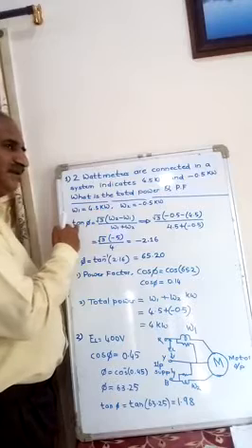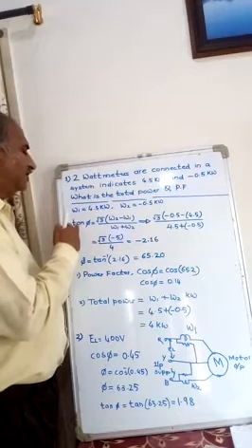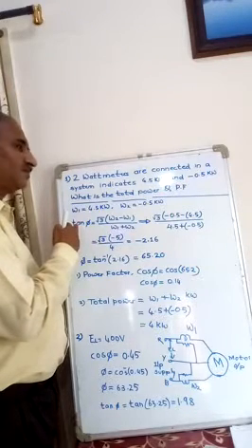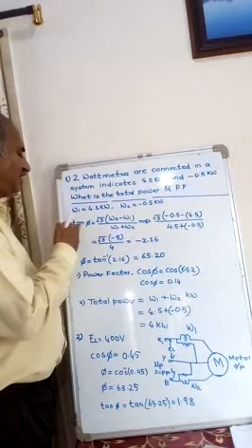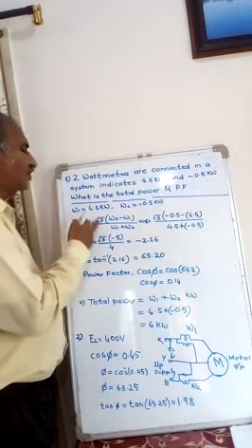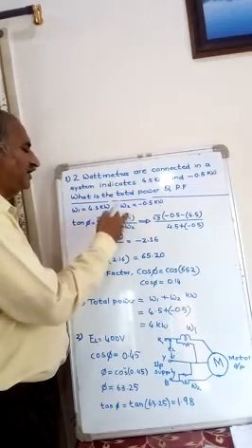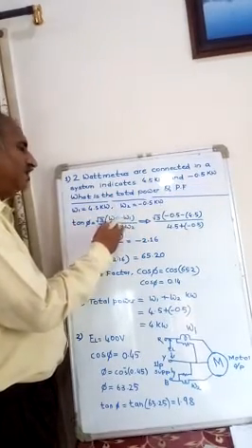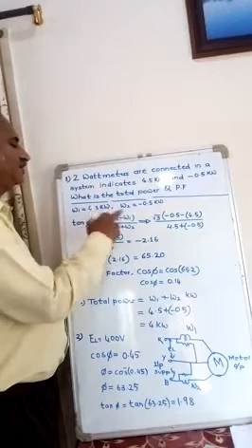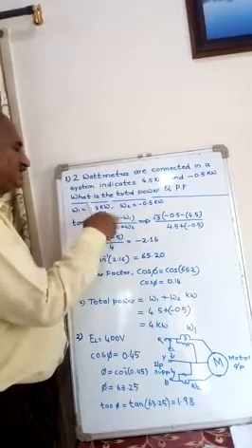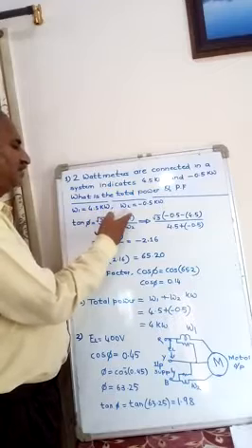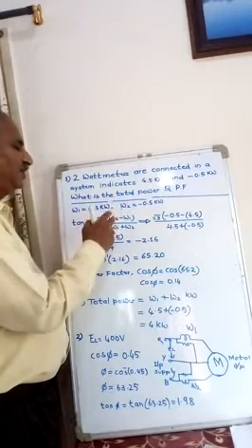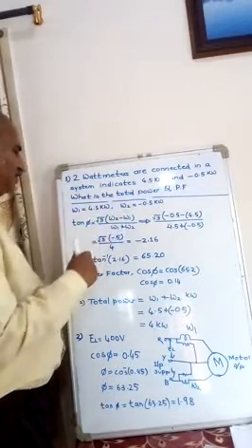Then second one, yesterday we have seen the estimation of cos phi, the power factor. Before that we have seen the final expression: tan phi equal to root 3 (W2 minus W1) divided by (W1 plus W2). In a few books W1 and W2 may be interchanged. You can refer to anyone, either W2 minus W1 or W1 minus W2. There is nothing different. Okay.